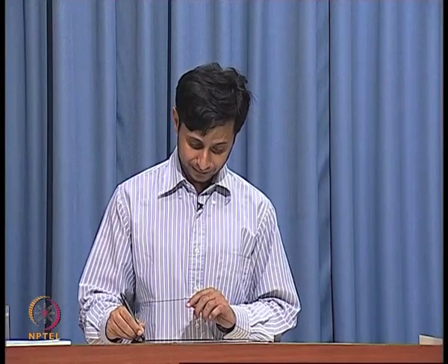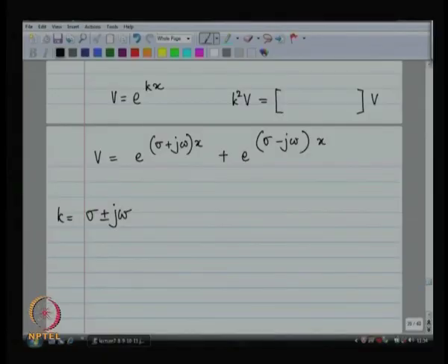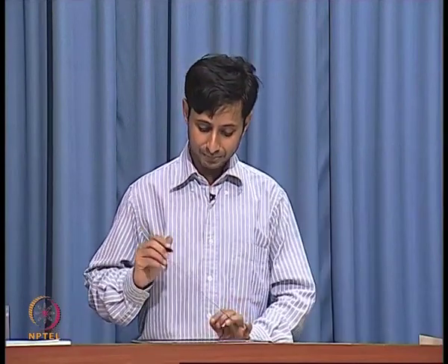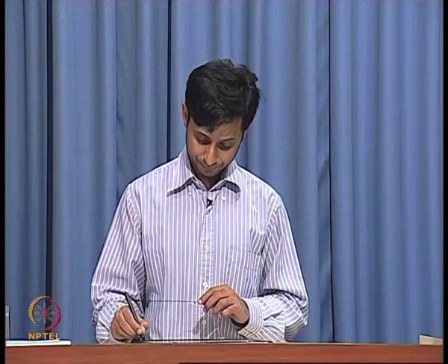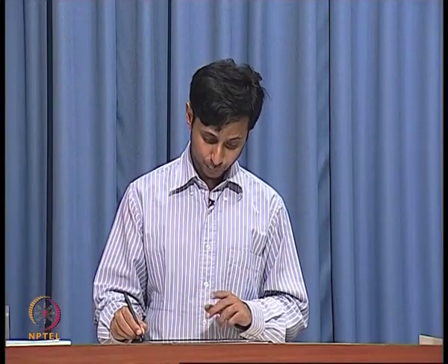When the resistance and conductance are present, like in the previous lecture we discussed, we will use the phasor notation, because it is going to be easier for us when we use the phasor notation. We are going to assume that all of these are sums of sinusoids. We are going to break up any signal into its composition in terms of sinusoids, and we are going to treat each sinusoid one at a time, right. Each sinusoid is going to create a forward and backward moving wave, which is slowly being attenuated by this factor sigma. That was my solution in the previous class.